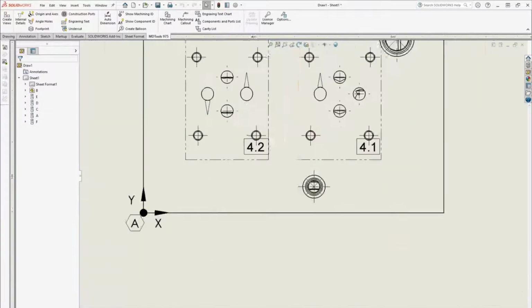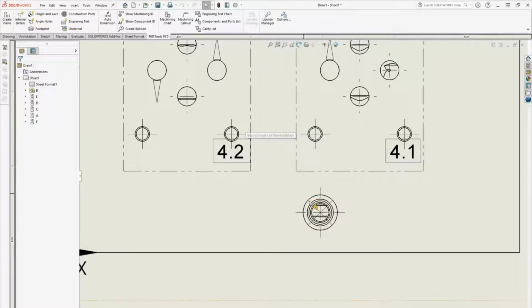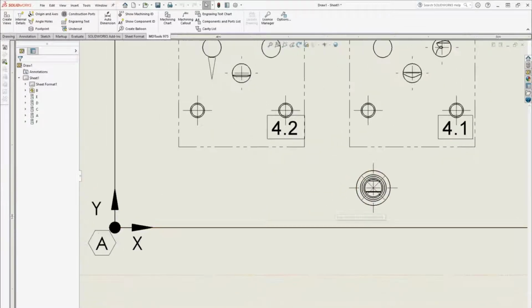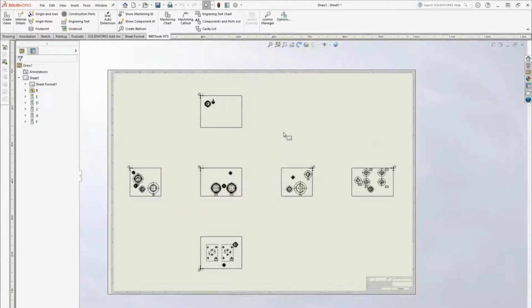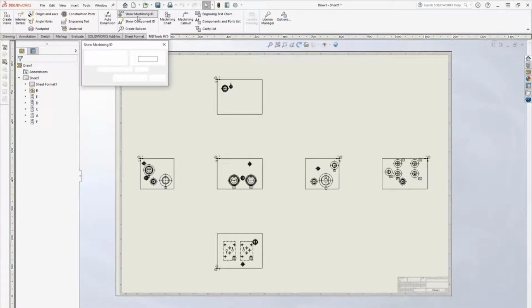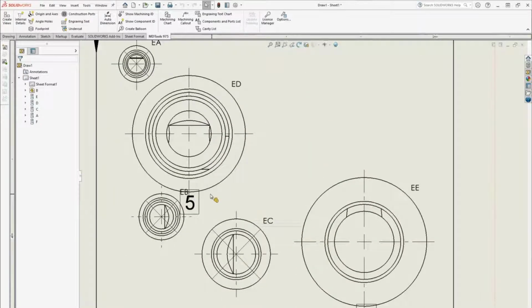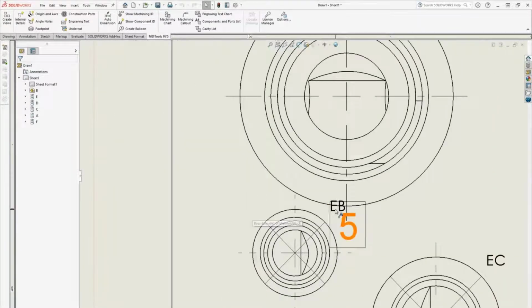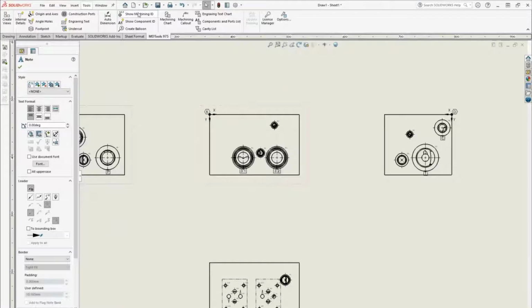If we zoom in a bit, we see the engraving, we see the direction for the inclined drills, we see a cross for the construction plugs, origin, face name for each drill. We can show the machining ID, which is basically that letter. If machining IDs are overlapping, you can just move them very quickly in each face. And let me save my drawing.